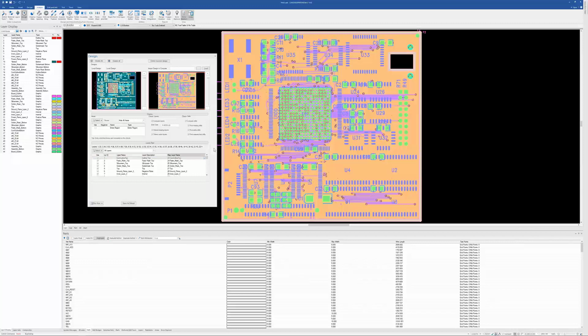One thing I was working on with a customer yesterday is they want to compare their panelized tool data to the original Gerbers they sent to their fabricator. Well, one of the options here is to either run inside the board outline, so I could define the board outline and it only runs in that area, or in a selected area, and I can actually select an area to run the analysis.